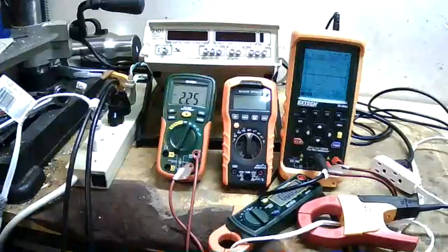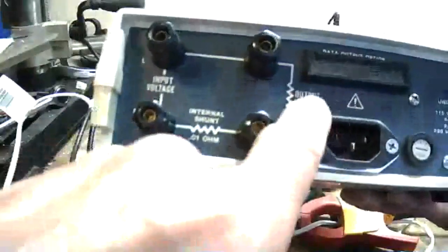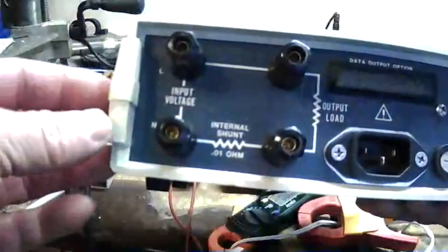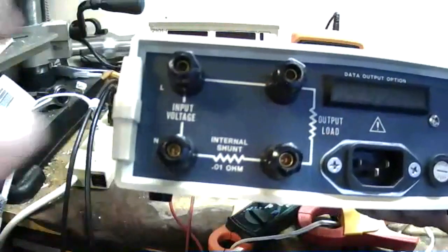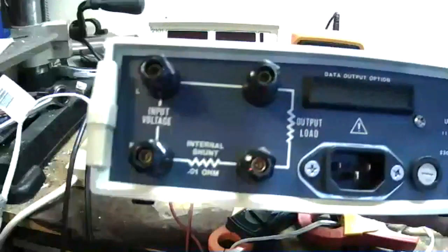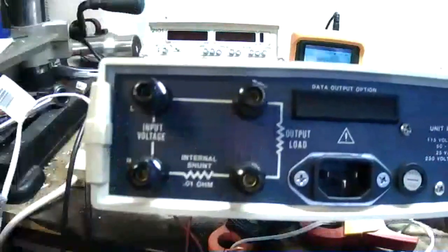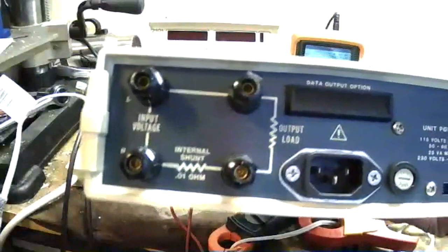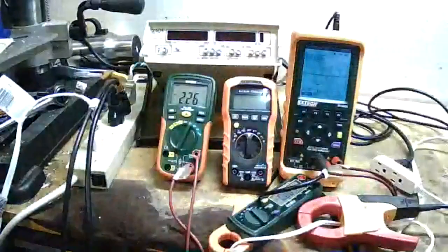I'll show you what the back of the watt meter looks like. I have another one here. And the back of the watt meter looks like this. Input voltage, output load. These are very nice devices to use. Now, the downside is you have to break the circuit, because you put the input voltage here, you connect the load, in this case, the drill press on the other side. There's an internal shunt that measures the current, but then it displays